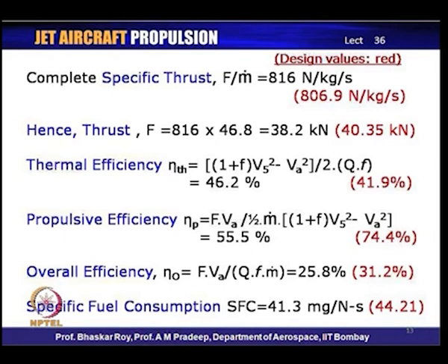So, we have estimated the off design performance of the entire engine, and it tells us that overall efficiency is lower than the design point efficiency, the thrust is lower than the design point thrust, but some of its other figures of merit are good. The specific thrust is actually marginally higher than the design point, and the specific fuel consumption is indeed lower than the design point specific fuel consumption.